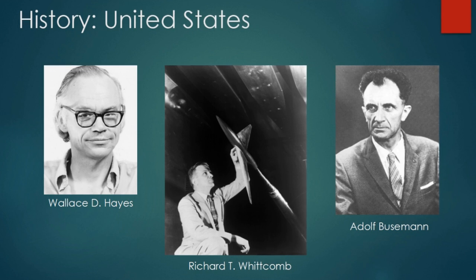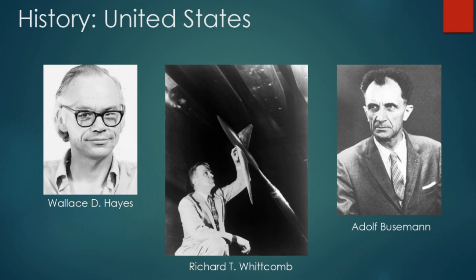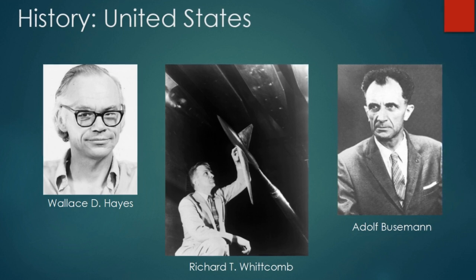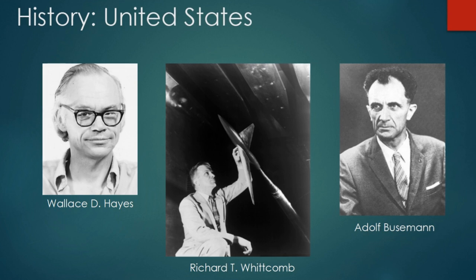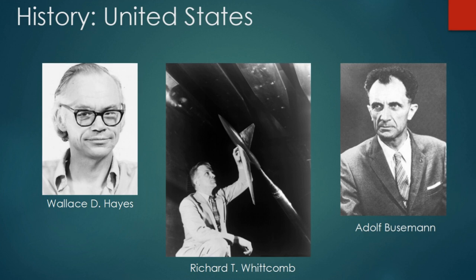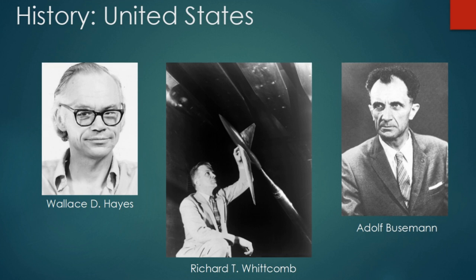He talked about the difference in the behavior of airflow as speeds approached the critical Mach number, where the air no longer behaved as an incompressible fluid, whereas engineers were used to thinking of air flowing smoothly around the body of the aircraft at high speeds. It simply did not have the time to get out of the way, and instead started to flow as if it were rigid pipes of flow, a concept Busemann referred to as stream pipes as opposed to streamlines, and jokingly suggested that engineers had to consider themselves pipe fitters.